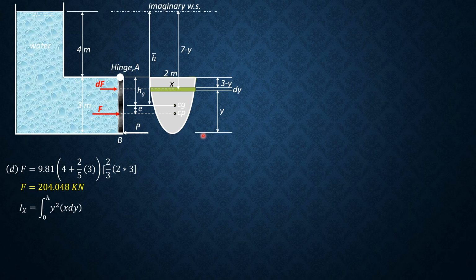So the distance from the x-axis to every element of the horizontal strip is y, it is constant. And the formula for moment of inertia of area is the integral of the constant distance squared, y squared dA, where dA is x times dy. So y squared dA is y squared x dy.